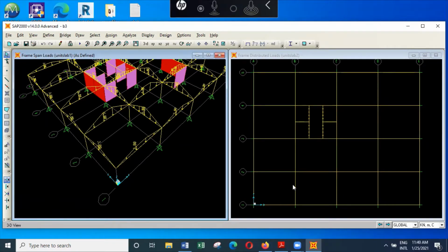The thickness of the slab will be more than 150 millimeters. And you will find that, with a thickness of around 175 millimeters, you will be fairly comfortable. But on the other hand, it's also possible to have a second beam this way, so that the maximum span will be reduced to 3.75 meters.